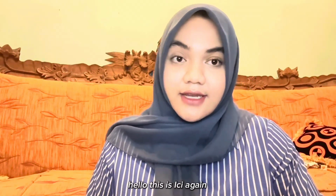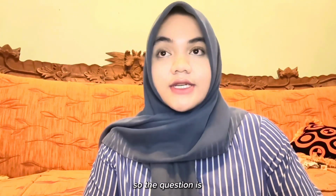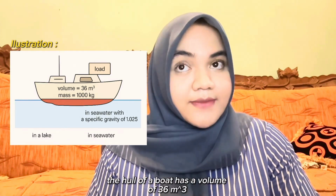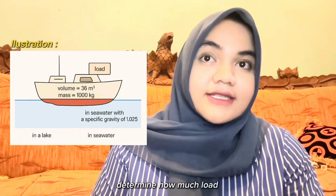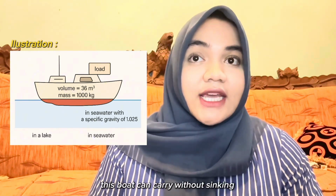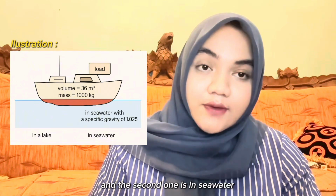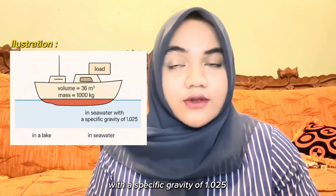Hello, this is Ichi again, and right now I want to solve question number 9. The question is, the hull of a boat has a volume of 36 cubic meters, and the total mass of the boat when empty is 1000 kilograms. Determine how much load this boat can carry without sinking, first in a lake, and second in seawater with a specific gravity of 1.025.